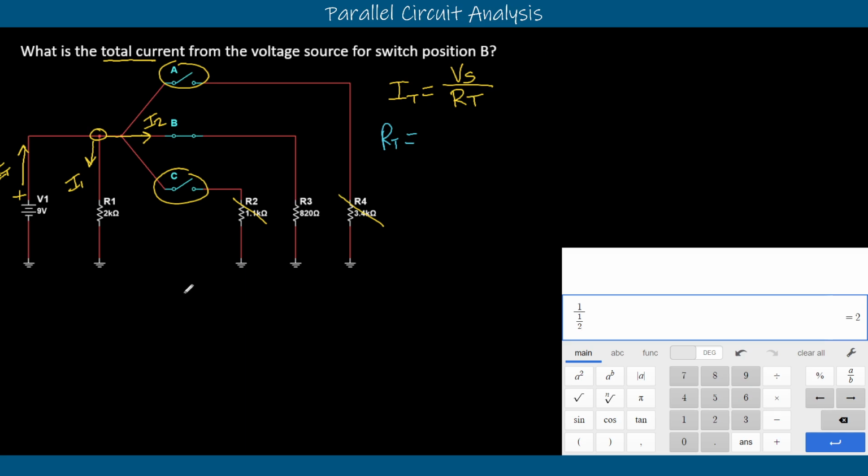So if we have 820 ohms and we want to make it kiloohms, we need to bring it from our base location and move it forward by 3 and put our decimal point there. So now we have 0.82, that 0 doesn't matter anymore, kiloohms. Right? So we'll leave our 3 at 0.82 kiloohms. And that's how we can evaluate that.